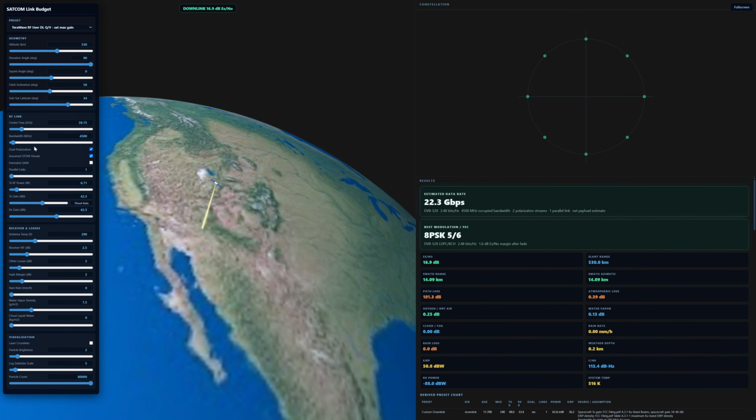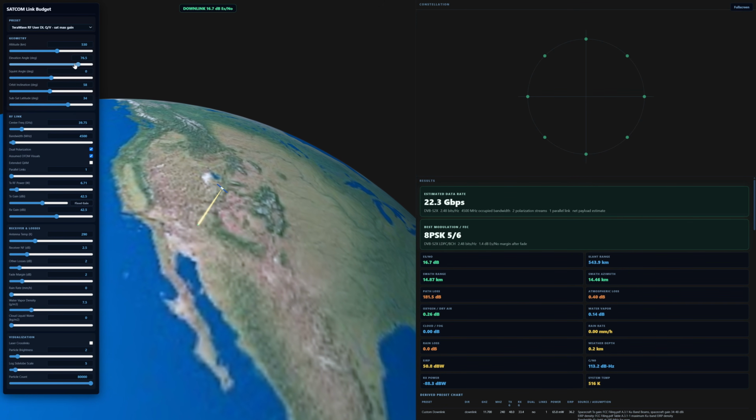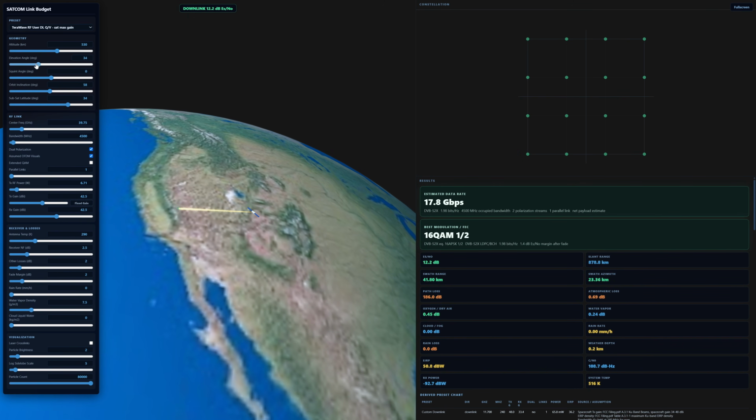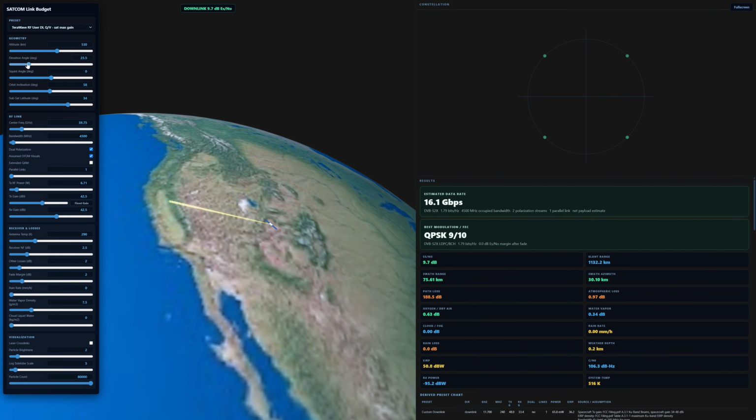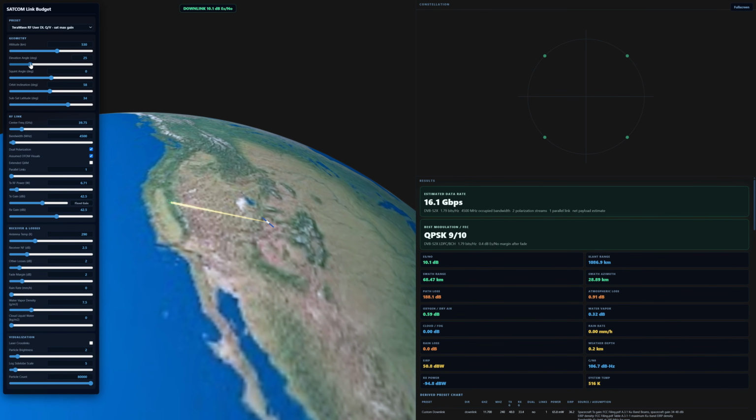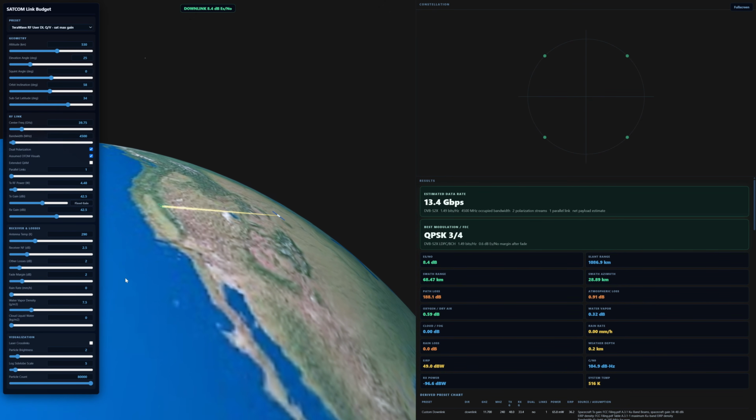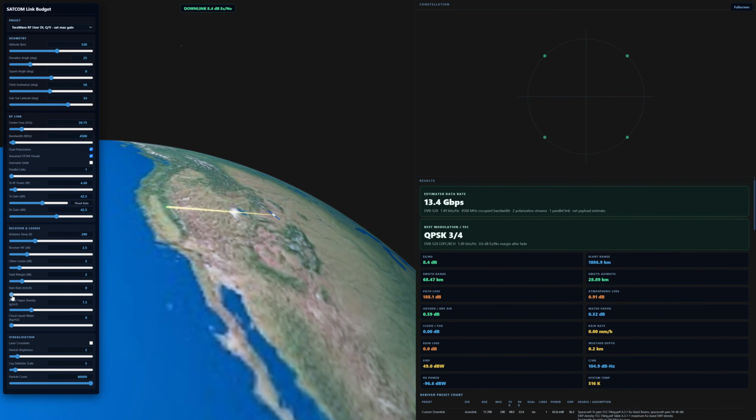As you see in my RF link budget sim here, in ideal conditions, you could get 2 bits per hertz, low code rate 16 QAM. Then, depending on your elevation angle, you would need to use lower code rate QPSK. So typically, you get around 10 to 15 gigabits per dual polarization link. The listed minimum elevation is 25 degrees, and there, even a light drizzle of rain would knock out the link without decreasing bandwidth and further decreasing the data rate.